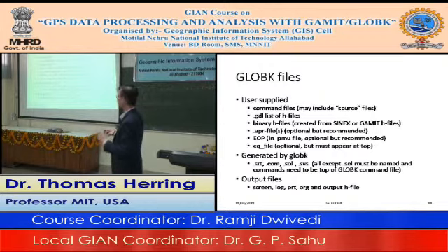We will ultimately need to use this. There's always one of these already for the ITRF 2008 system because of all the antenna changes that affect that in ITRF 2014. Files that are internally generated by GLOBK. There's a little binary file called .srt, which you don't normally worry about, but it is the actual time-sorted list of your files.